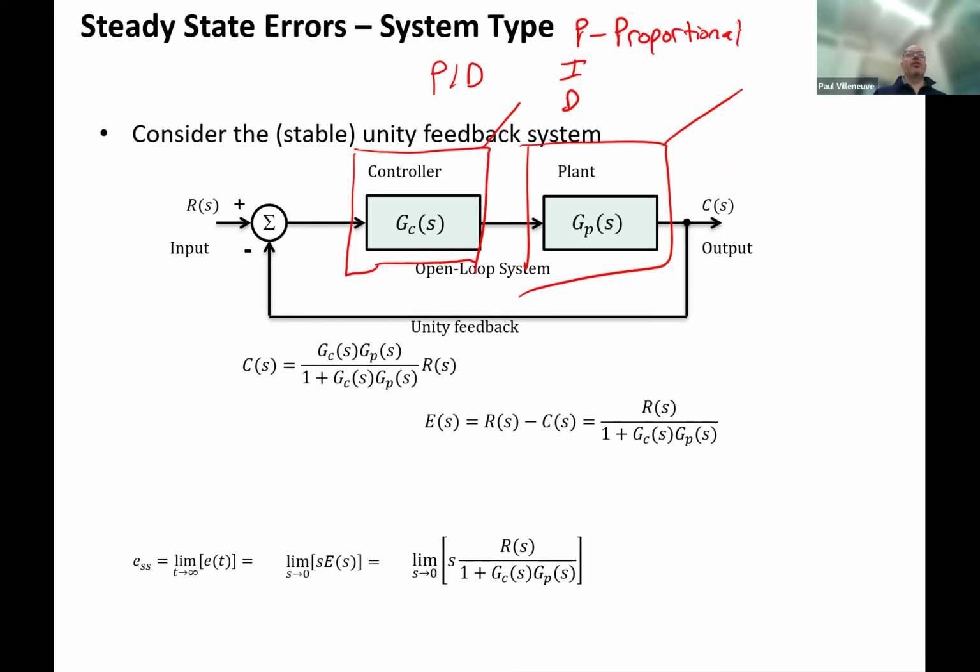It's a proportional controller. So if you have a proportional only controller, you hit it with an input, whatever that input is, and then it outputs a signal that is proportional to the input. So this is essentially multiplying it by a constant K. The I, as everybody said, is integral. And this is derivative. This here we have the integral, and this here we have the derivative signal.